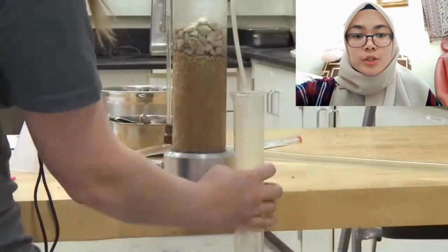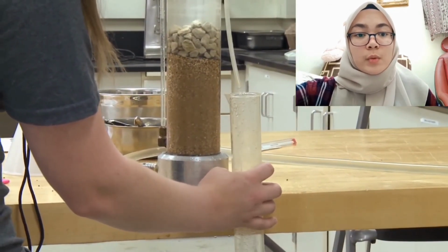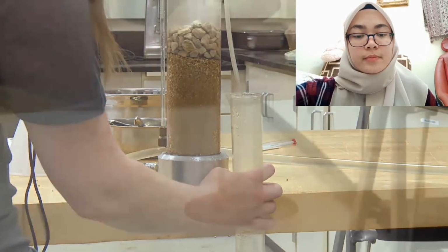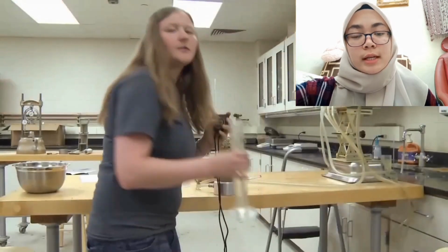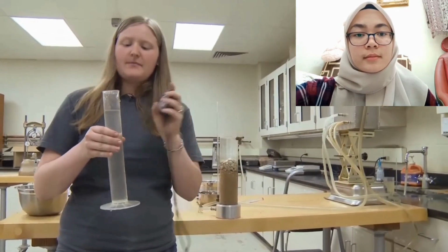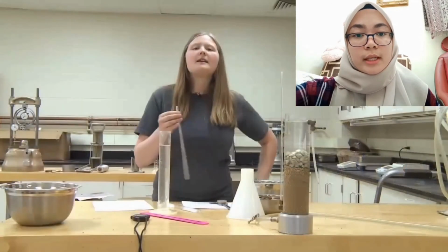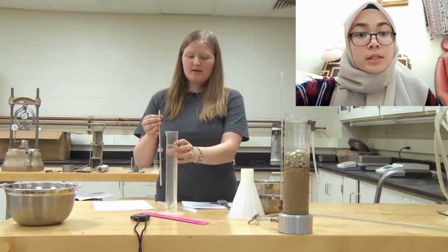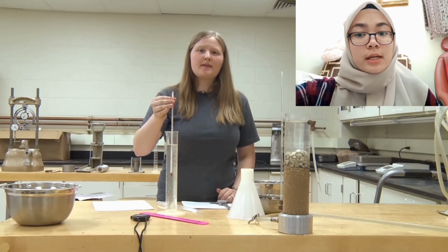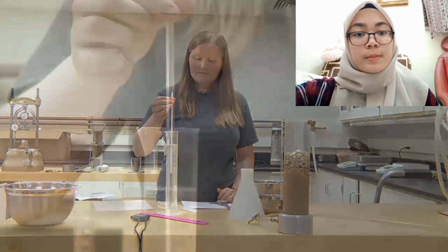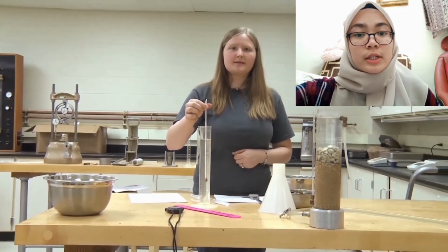The water reached 250 ml. Record the time and repeat the sequence 3 times. The average will be taken to use in the calculation. Next step is to measure the water temperature. Measure the temperature of the water in the cylinder and record it for the temperature correction in the calculation. Complete the measurement 4 times to accumulate enough data to perform the calculation.